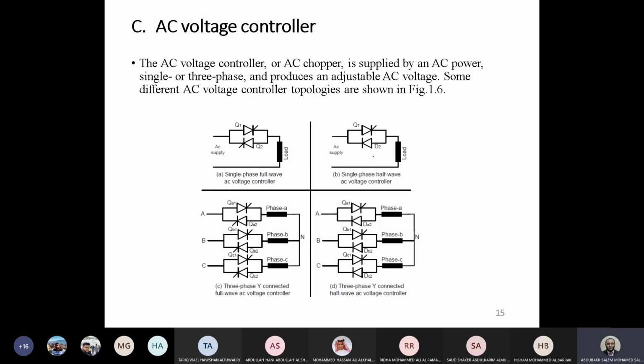All of the time, guys, AC loads need 0 average volt, like the voltage what we have in homes. Okay, the positive and negative half cycles should be equal all of the time. So the average value should be 0. So we don't recommend this circuit in industry. Okay, we prefer to use this one. This is single phase, and this is for 3-phase circuit.